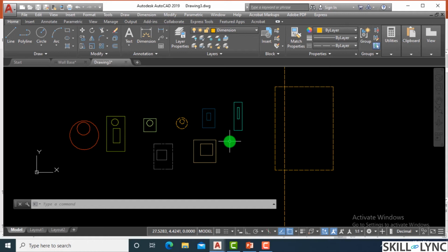Like you can give a color by the ACI, the AutoCAD Color Index. You can give the color by the true colors or the AutoCAD color book. So you can assign colors by RGB, HSL, any other thing. So AutoCAD has a library which is the ACI, which can be used for defining the color. So normally the CAD standard uses the ACI. That means the index color. You identify a color by a number, like 19, 20, 38, right?